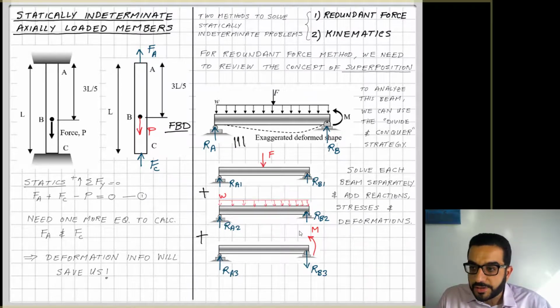So it's pretty handy. In some load cases, I can use information that is in textbooks. For a point load on a beam, a lot of textbooks give you reactions, or you can actually memorize them. You can calculate the deformation at one point from tables and textbooks.